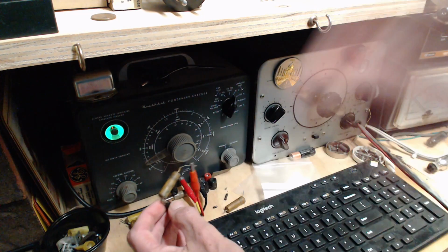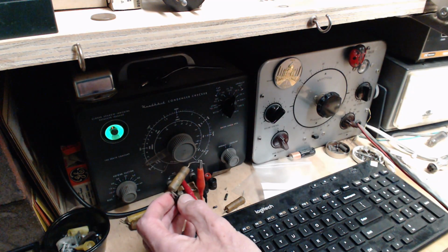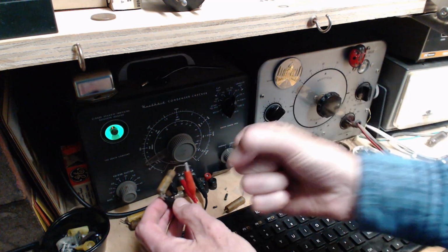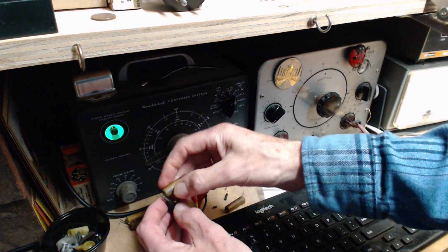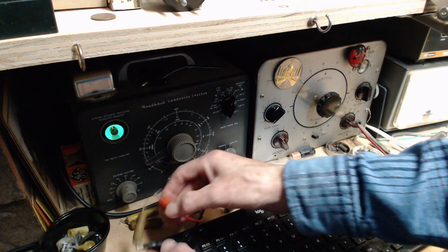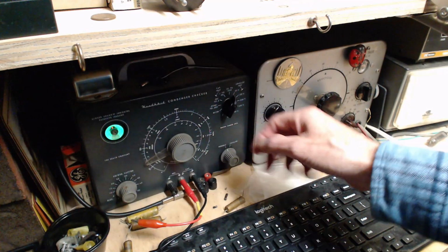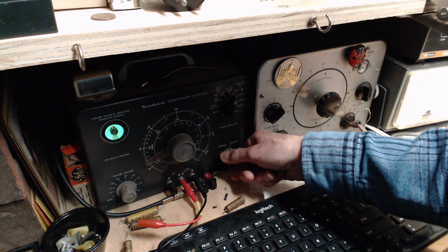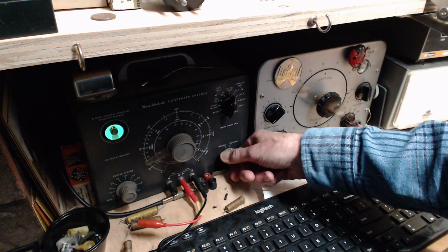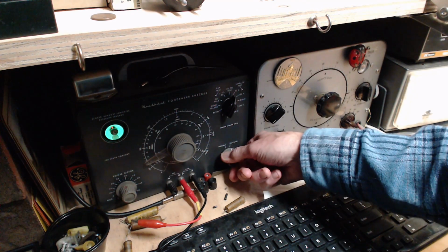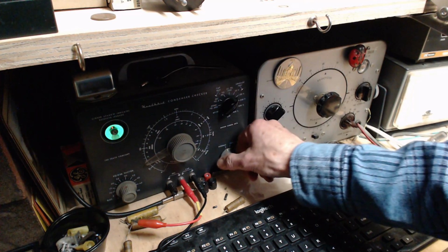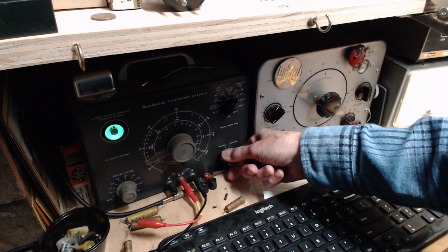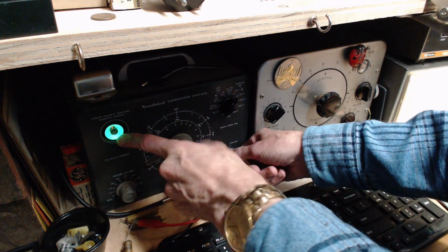A capacitor like this that's got, say, 120 volts of alternating current across it, maybe it's right across the line, that guy's getting beat up much more than one like this. But let's see what's happened. So watching the eye, here we go. Well, that's one of the better capacitors for sure. It's opened almost all the way. So at 150 volts though, the leak is too much for my machine. The eye is not opening at all.